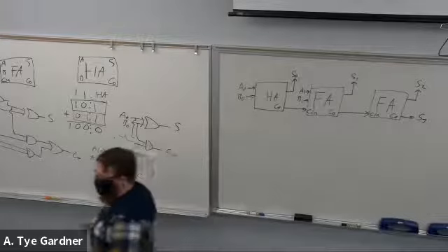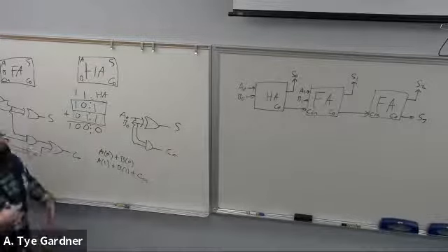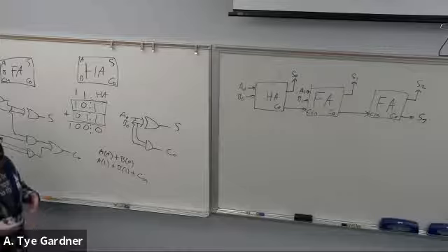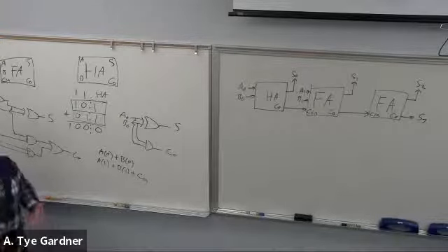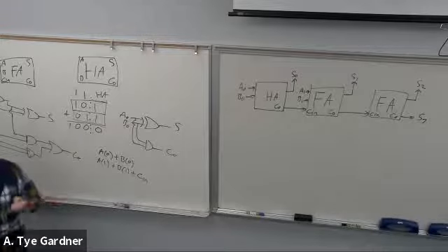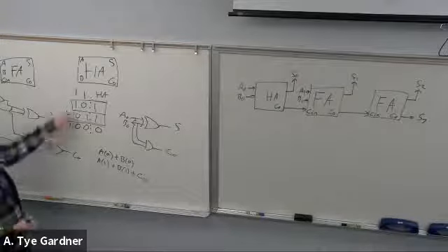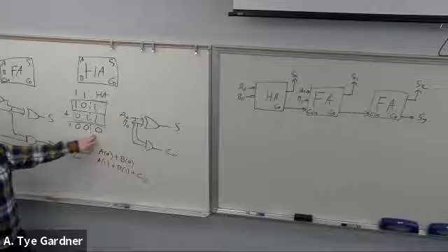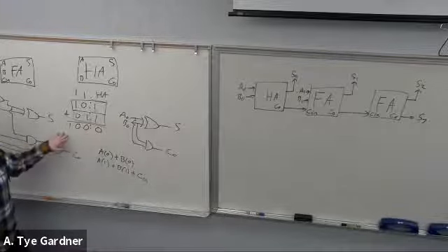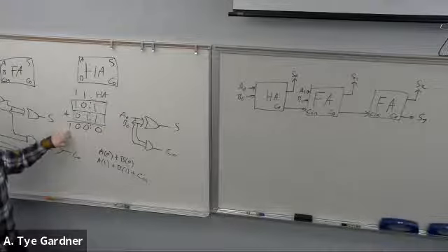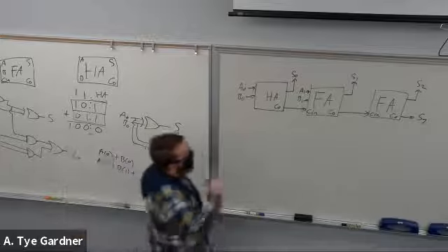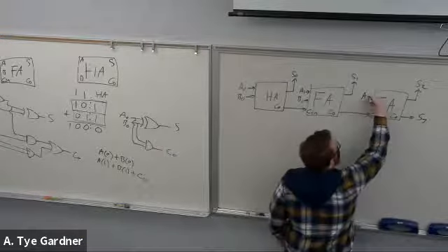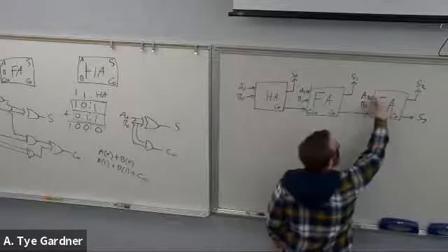So that gets used 2 different ways. One way is we just call it the overflow. It just carries an overflow flag saying we added up to too big of a number to store in 3 bits. The other way is we can consider it as the 4th bit of the sum from 2 3-bit numbers, right? Because if we add 2 3 bits, I can end up with 4. I won't end up with 5 bits ever. So depending how I designed my architecture for my circuit, I may or may not be able to save that most significant bit, the S3. A2, B2.